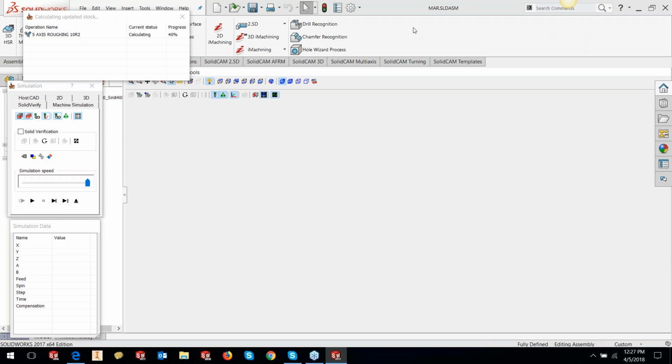The term multi-axis roughing is sometimes deceiving, because in most of the cases the user thinks that no matter what my wall is, the tool axis is always going to be parallel to my wall, but that's not the case. The tool axis will only be normal to your floor surface. So whatever the surface that is generated at the end, the wall surface, will always be normal to your floor surfaces. So that's one key thing that you need to understand in multi-axis roughing.